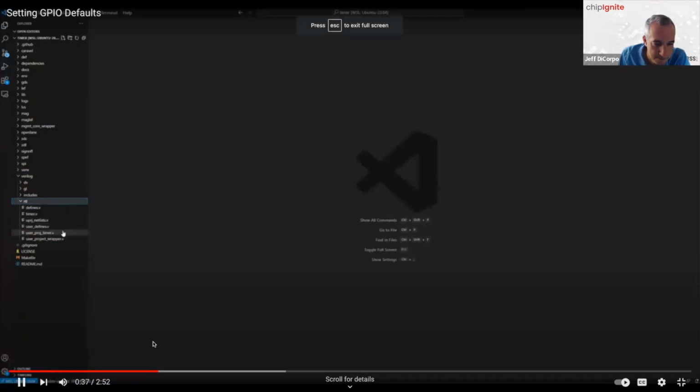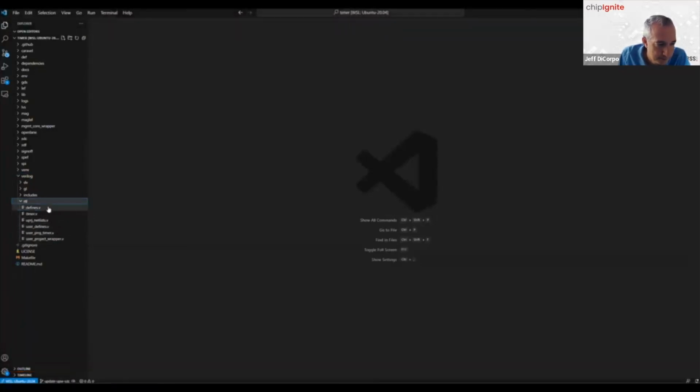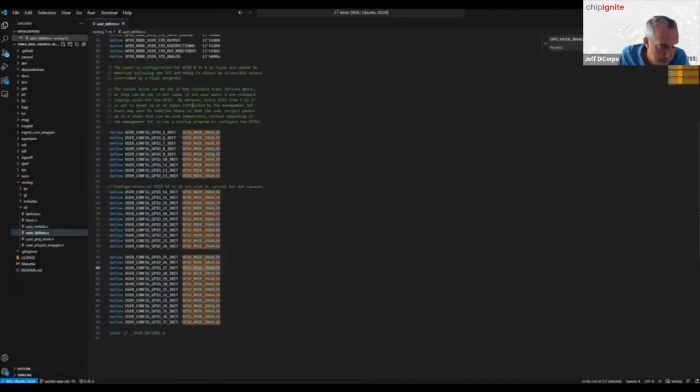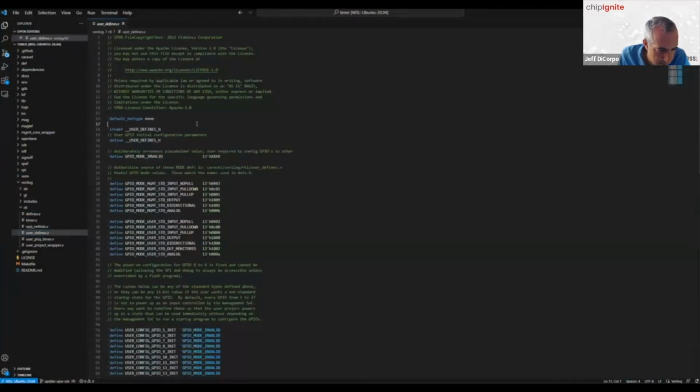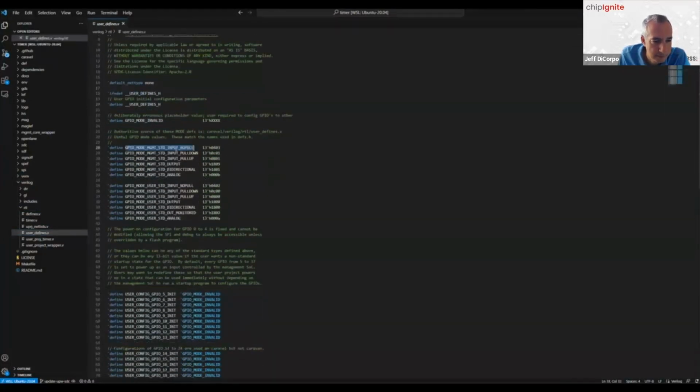The Verilog RTL user-defines.v file. In this file, you will find a set of predefined default configurations. One set of default configurations map the corresponding GPIO to the user area, while another set map the GPIO to the management area. The user area configuration values begin with GPIO_mode_user, while the management area configs begin with GPIO_mode_MGMT. Within each of these groups, there are configurations for setting the GPIO as digital input, output, or bidirectional signals.